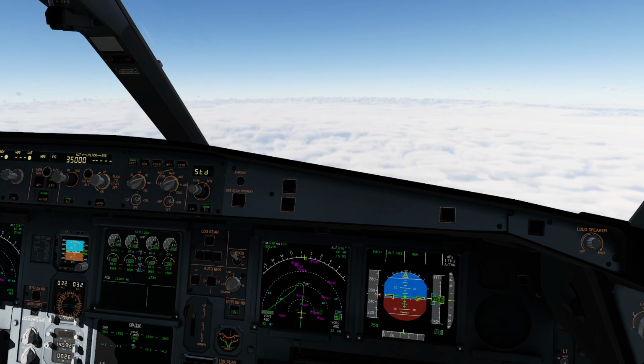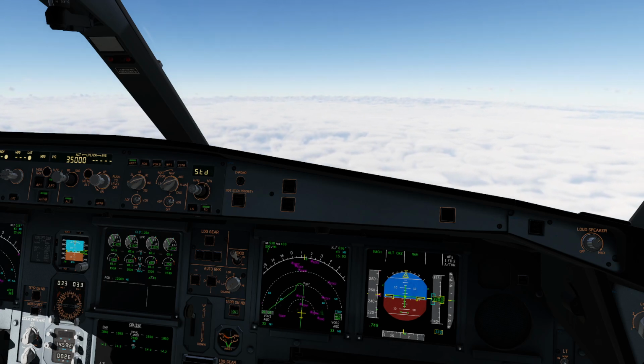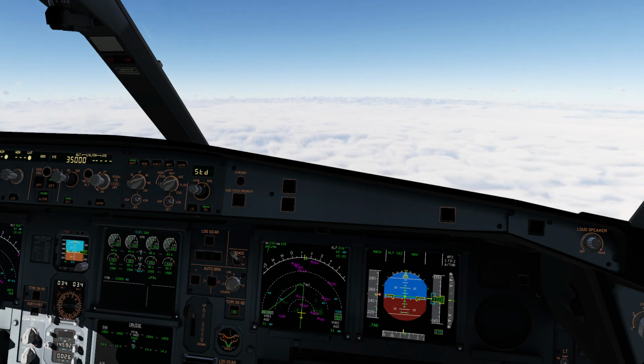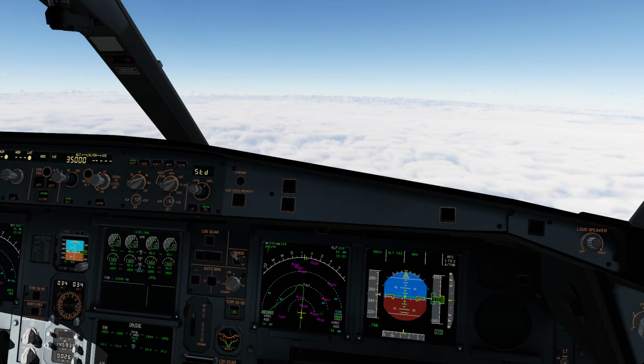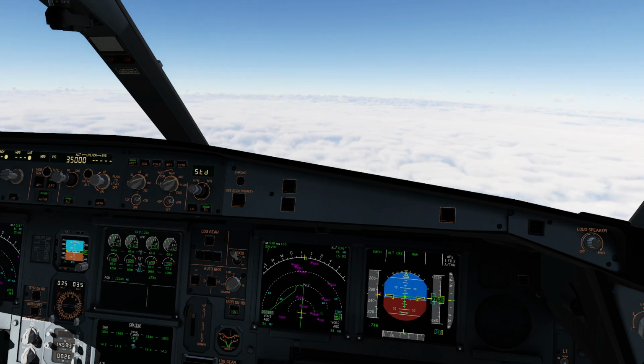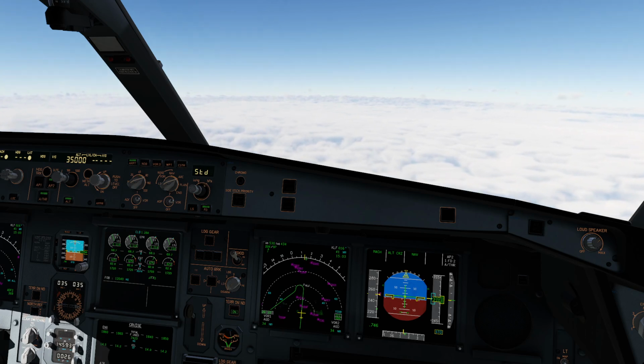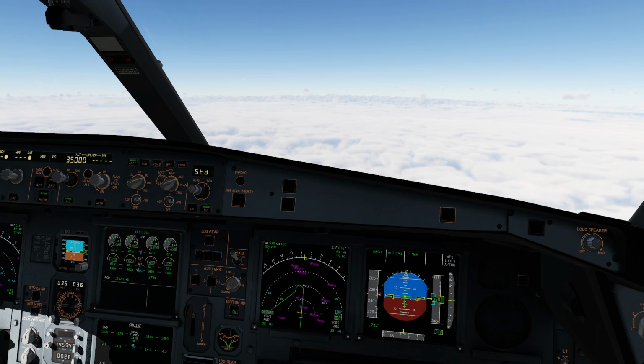When the oxygen mask is on, the pilot flying is going to initiate the emergency descent by turning and pulling the altitude knob, turning and pulling the heading knob, and pulling the speed knob. Announce the FMA, and if the auto thrust is not active, put the thrust levers into idle. Finally, extend the speed brakes. The pilot monitoring, after putting on the oxygen mask, is going to turn on the passenger signs, check the FMA, and once established in the descent, start the DECOM actions.